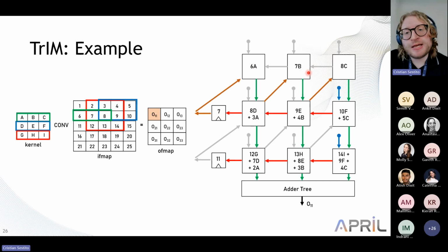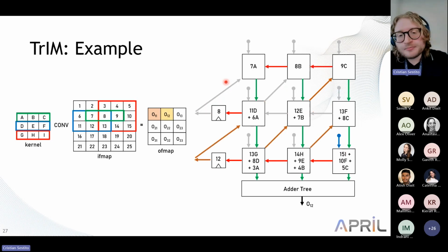So we have reuse. As you can see, in this cycle, from the external memory we supply only these two pieces of data, while all the other data are reused locally. So we're reducing the number of external memory accesses to finalize the convolution. And so on till the completion of the algorithm.